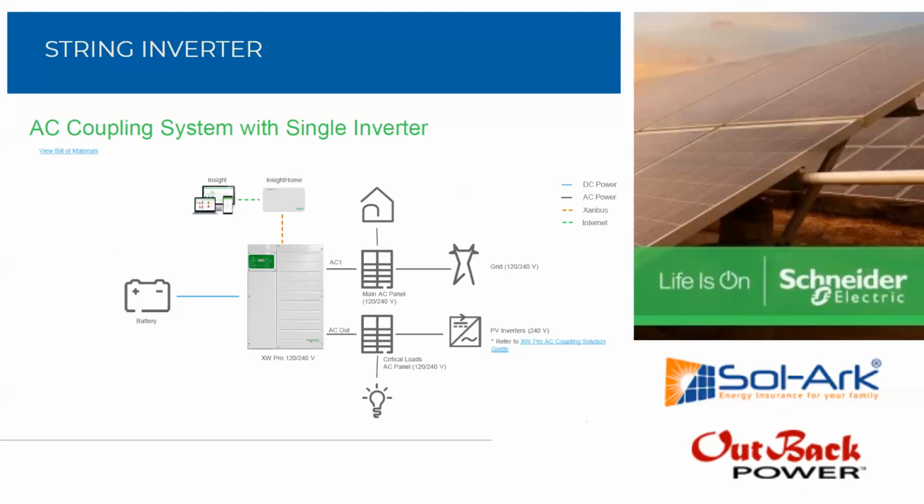And what is load control? Right now, you have to physically distinguish your critical load panel from your main service panel. And this can be somewhat cumbersome. You have to physically move any loads that were previously on your whole home service panel into your sub panel.